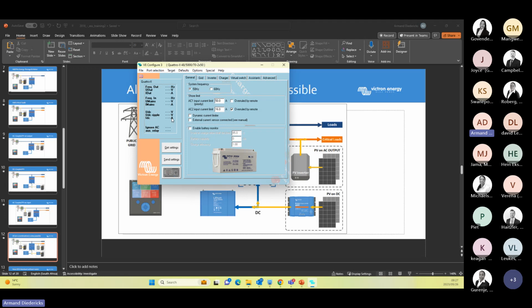So what a ripple is, if the cables are too small and not calculated correctly, you'll have a DC ripple, and that will cause your inverters to toggle. So it will switch on and off, meaning that it can't handle the inrush current, and the voltage drop between the DC to the inverter and the battery, so the inverters will toggle.